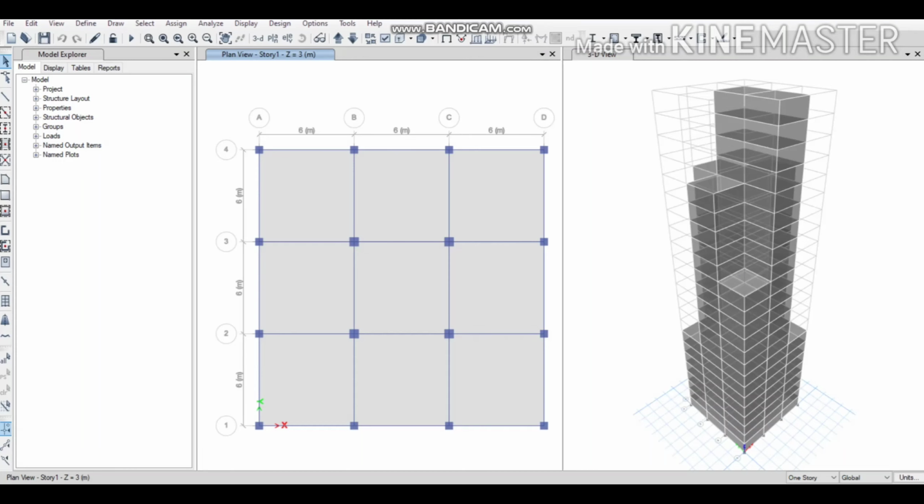So in our previous video on the tall buildings design project assignment, we have seen the application of live loads, dead loads and cladding loads, and the analysis and design check of the particular project building. So now let's add the seismic loads and run the analysis and design using the time history method and response spectrum method. For that, first we need to define the seismic load.